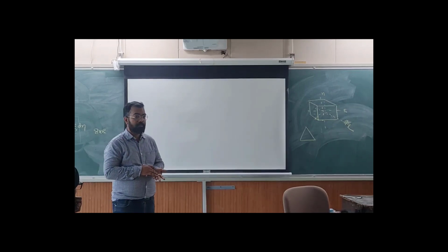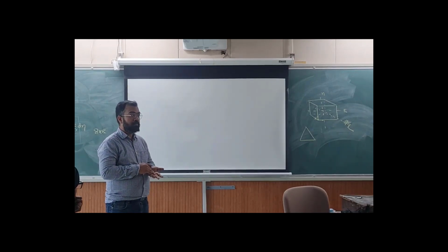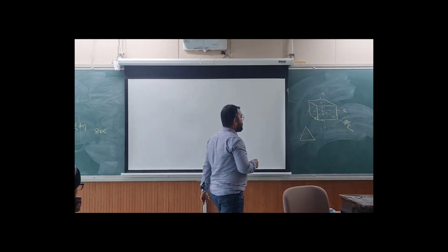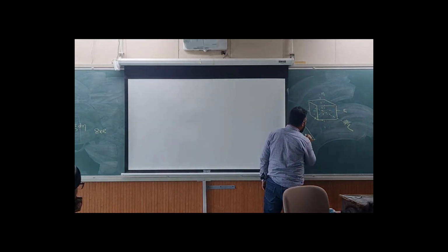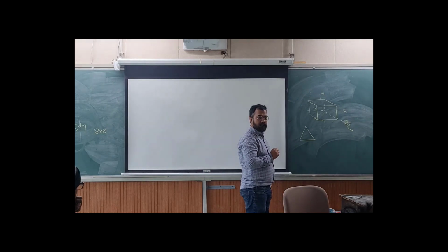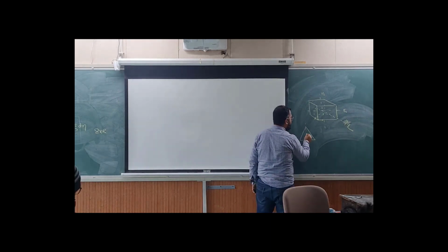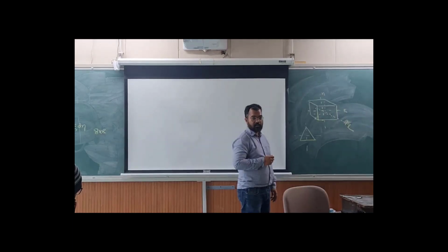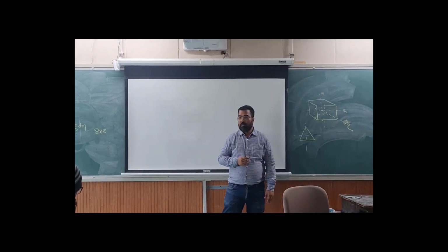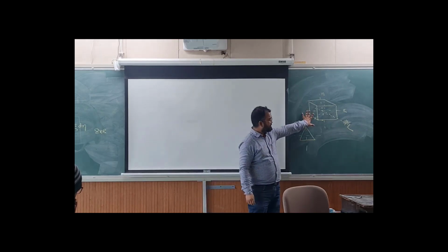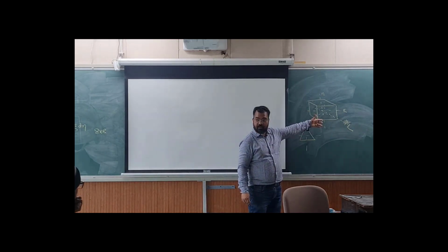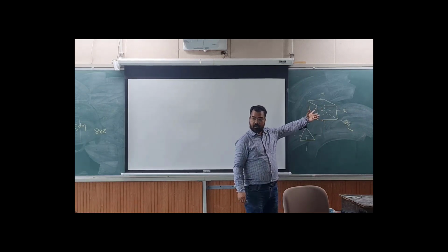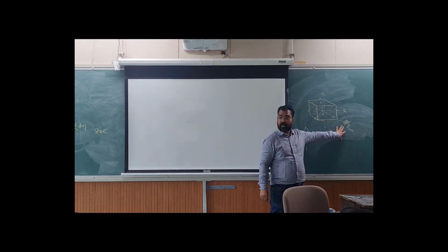So why, in that triangle case, can you not find it? Because in this case, how will you assign the local coordinate? You cannot map it to -1 and +1, no? That you cannot do. So what you have done in 2 dimensions, you have to extrapolate. So you have to make another one, and then you can imagine the shape functions will have epsilon, eta, and zeta. 3 things.